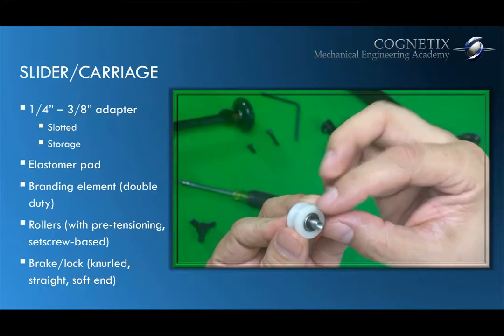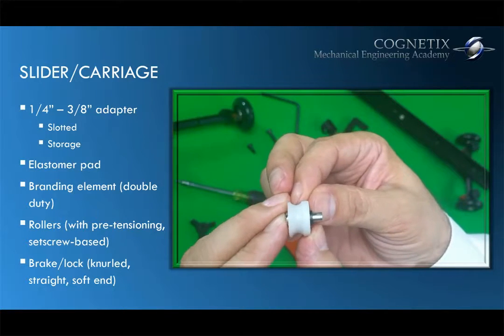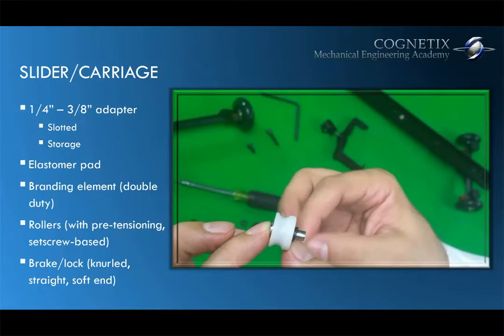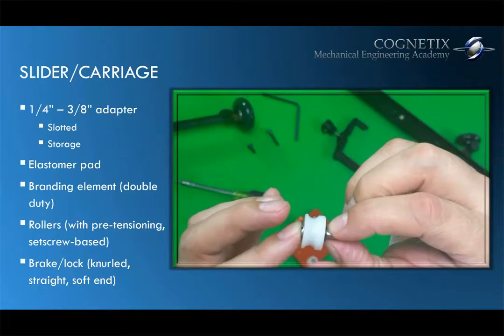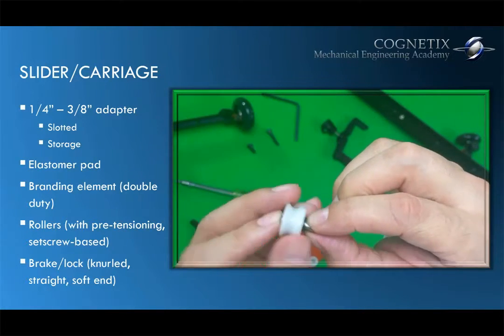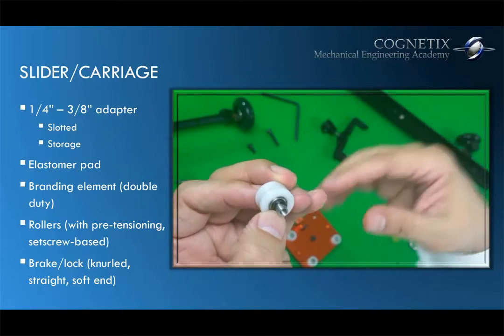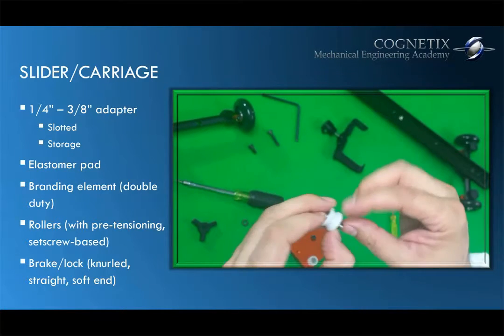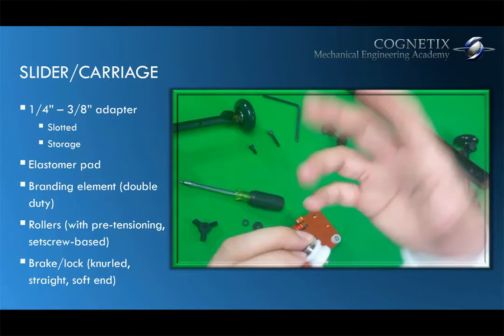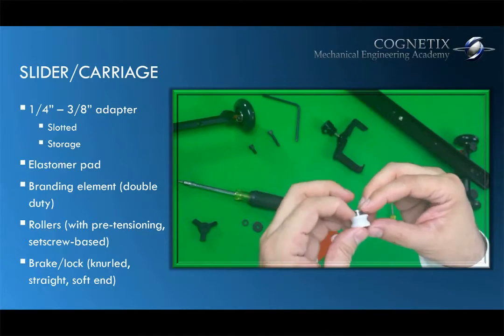This washer contacts the inner race of the other bearing at the other end and locks both inner races together so they're not rotating, but the roller is rotating along with the outer races. Okay, I hope that makes sense. Yet another mechanical engineering and design topic that we cover in the academy, in a lot more detail, of course, with engineering drawings and CAD modeling.